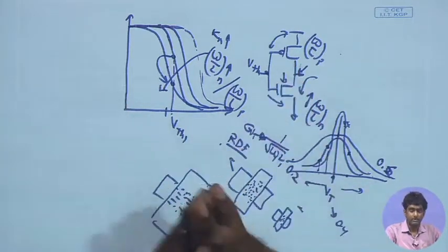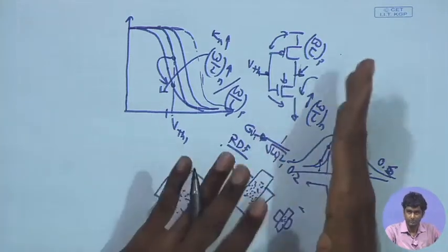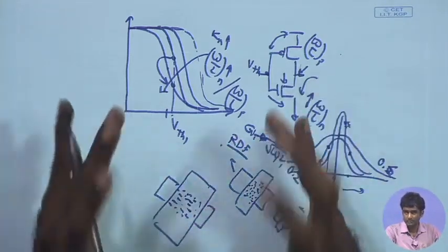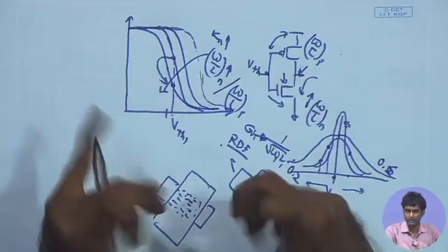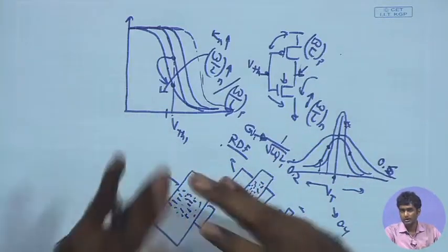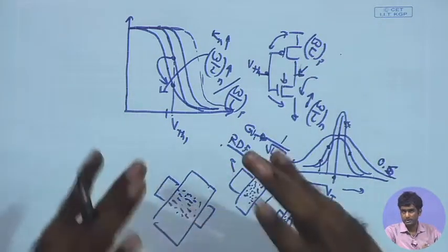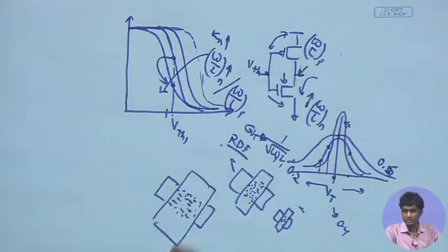You can end up converting a common mode disturbance into a differential signal because of the mismatch in the input pair or the load pair. So, whenever there are paired transistors and you have mismatch between them, it can lead to significant amplification of the common mode signal.